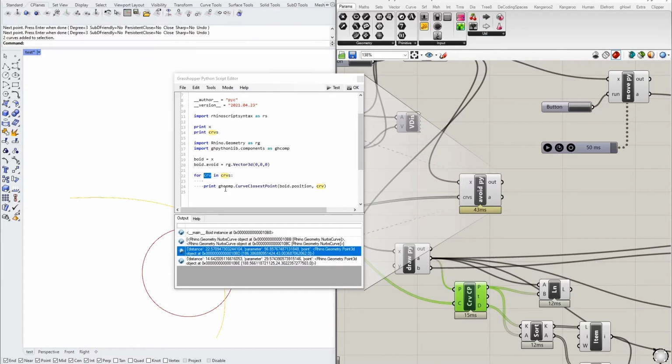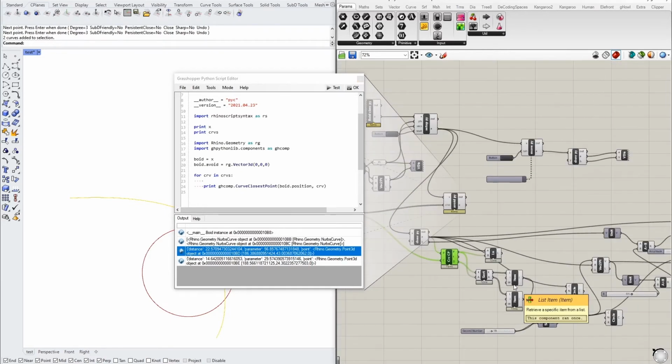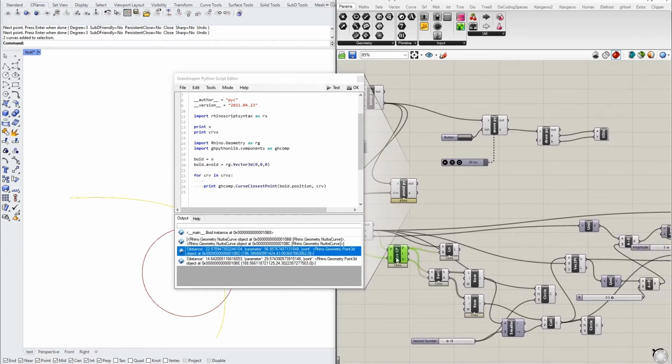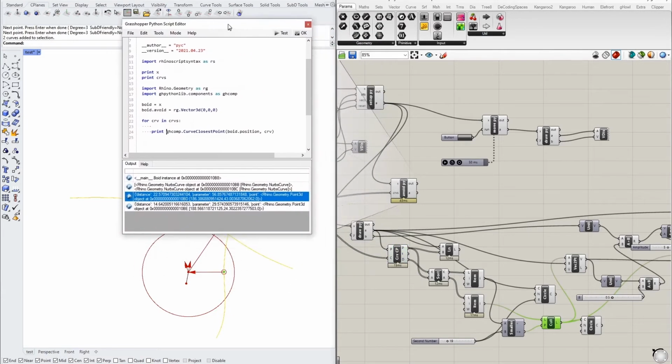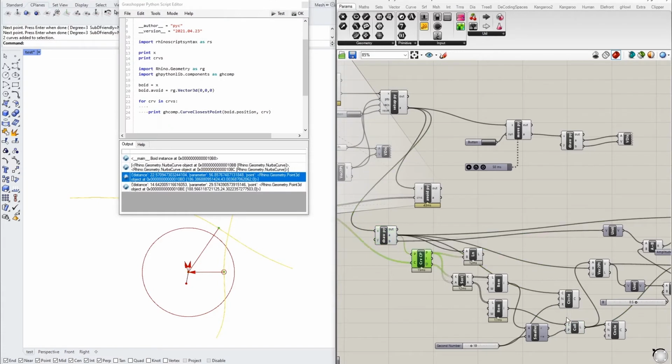The next step in code, we will deviate a little bit from the prototype that we made earlier, but to obtain the same outcome. So we have the curve closest point here, and we want to be able to obtain the closest point within the prototype. And we are going to look at how we can find the closest point amongst multiple curves. Instead of sorting the distance and the associated points from curve closest points and using the node to find whether the point is within a specified range, we will create 2 variables within the Python script.